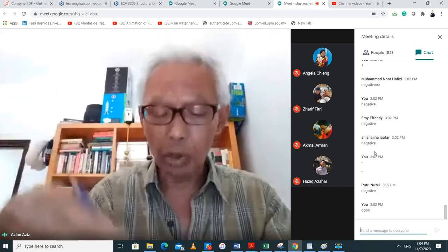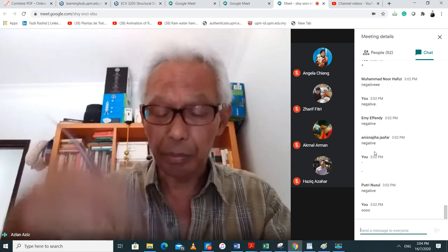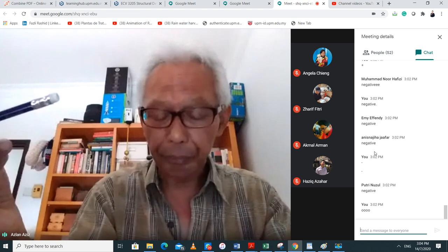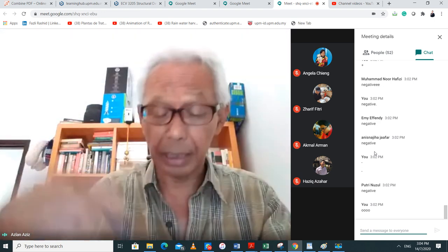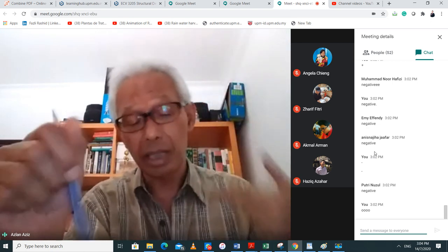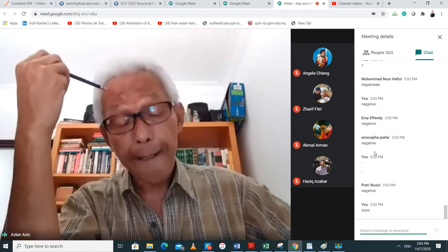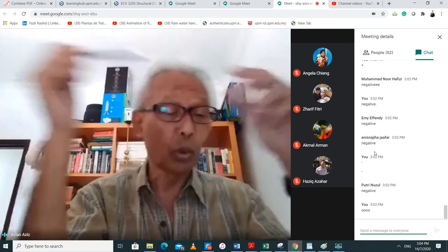All right, so you have this fill, it's settling as well, because you have dissipation of excess pore water pressure, additional stress. So you get negative skin friction in the soft clay, not in a dense sand. It wants to pull it down. That's why the arrow is downward. Okay. All right, so the phenomenon has been explained to you.